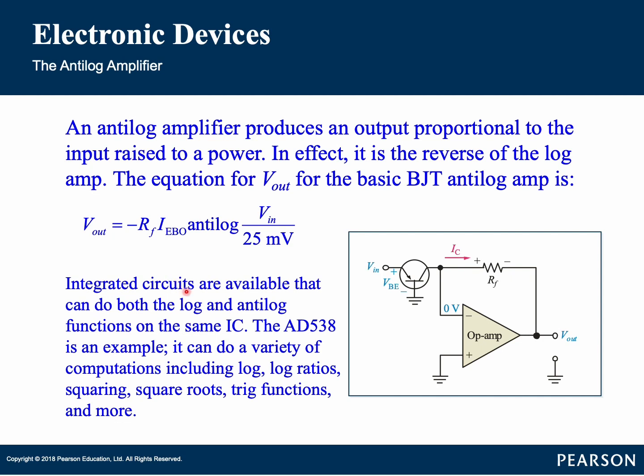Integrated circuits are available that can do both the log and anti-log function on the same IC. One of them is the AD538, for example. It can do a variety of computations including log ratios, squaring, square roots, trigonometric functions, and more.